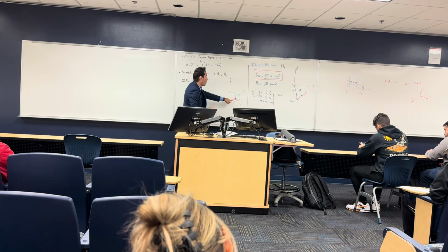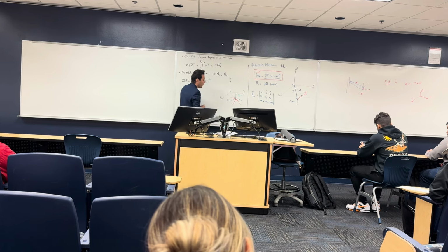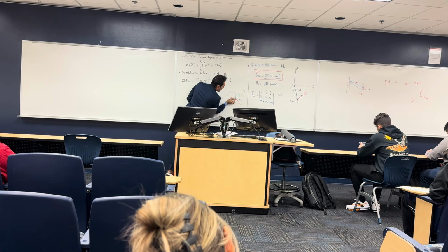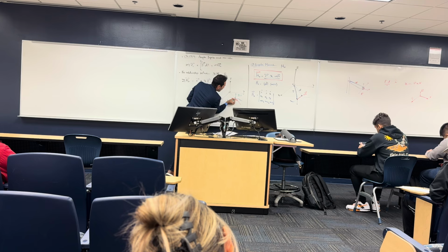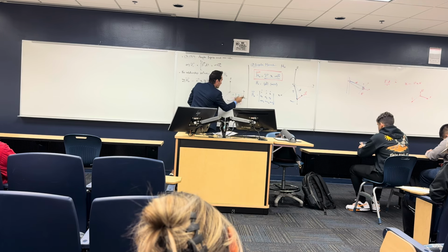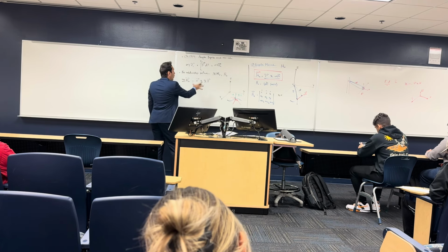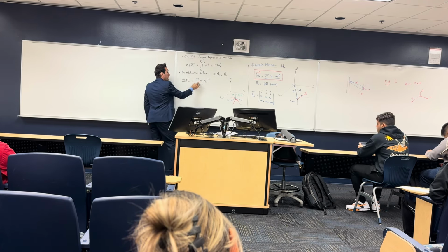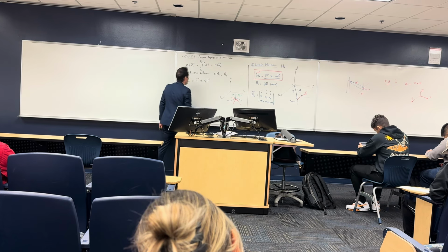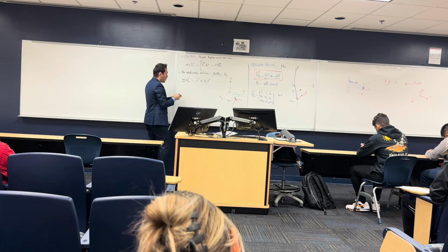The moment of this force: you need to find the perpendicular distance from point O to this force F, and this should be perpendicular. Okay, and this should be D. Once you multiply D by the sum of F, you will get the moment of these forces about point O. Or we take the position vector R from here to here, and multiply it by the vector of the forces. This is the general rule.